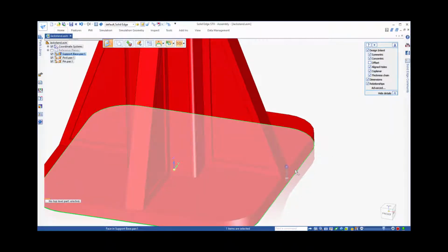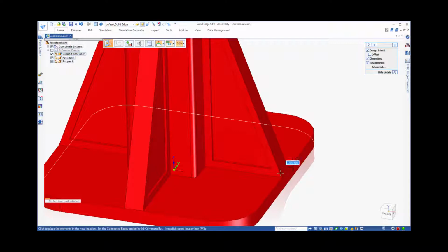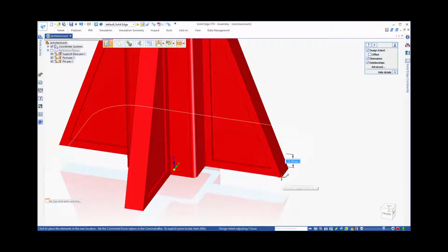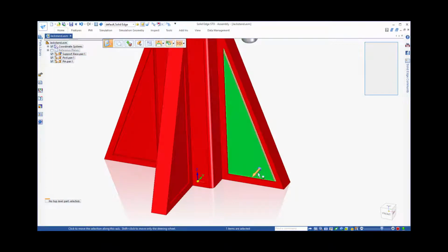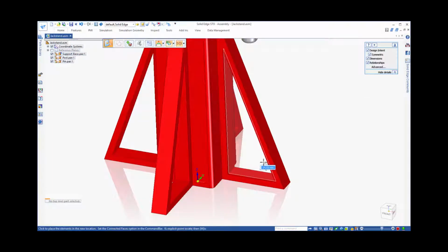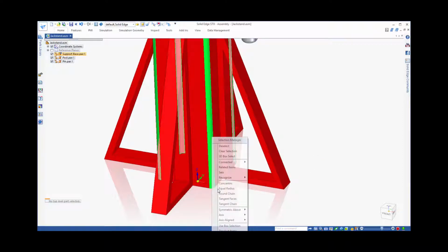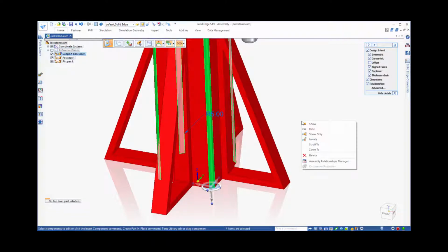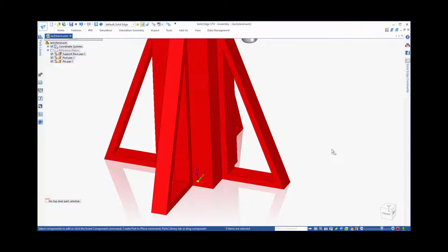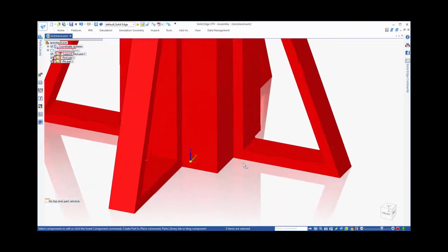to make the changes. By disabling the offset design intent, we can remove the bottom plate by simply dragging the bottom face up to the point where it disappears. We can use this same technique to remove the recessed area of the angled ribs. The Selection Manager tool enables us to interrogate the model automatically to detect and find all the rounded corners that contain the same radius, and in this case we'll use the selection to remove these rounds.